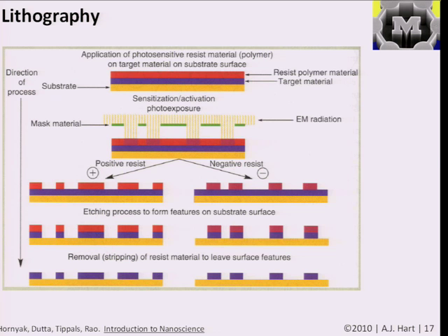You can have different types of this resist material. For example, if it's what's called positive resist, it means that the material is kept where you have not exposed it to light. If it's negative resist, it means that it's kept in the place where you do expose it to light. What actually goes on here is you shoot it with light, you expose it, and then you dip it in a chemical which will selectively dissolve the area that has not been stabilized by the interaction with light. That's what's called development. If you have a positive resist, then you want to expose to light the areas that you want to develop away.